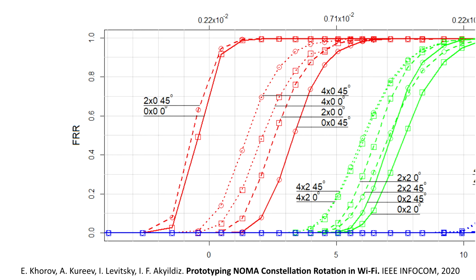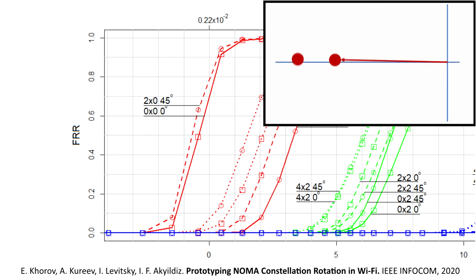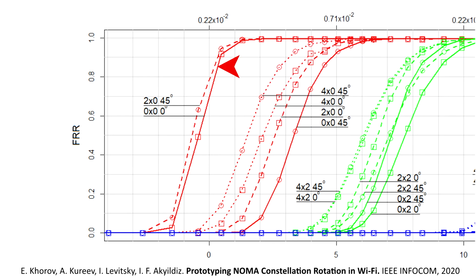In these cases, the phase noise acts in a perpendicular direction to the secondary BPSK, and hence has no effect on the reception. If we change the rotation, the situation only worsens. The difference here is 3.9 decibels of SNR, so rotation can really influence the reception.